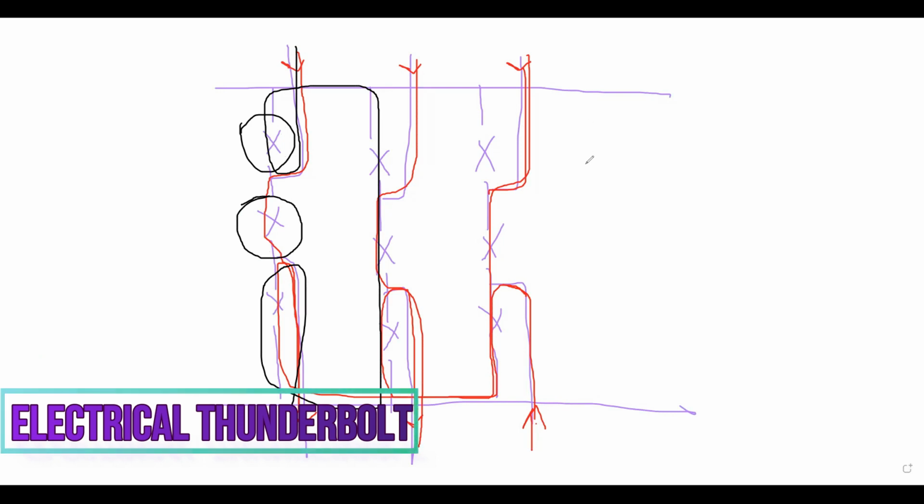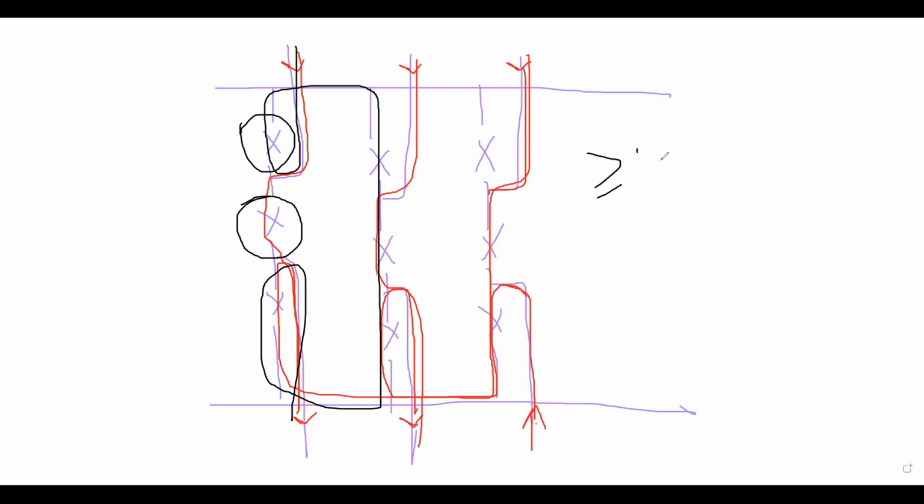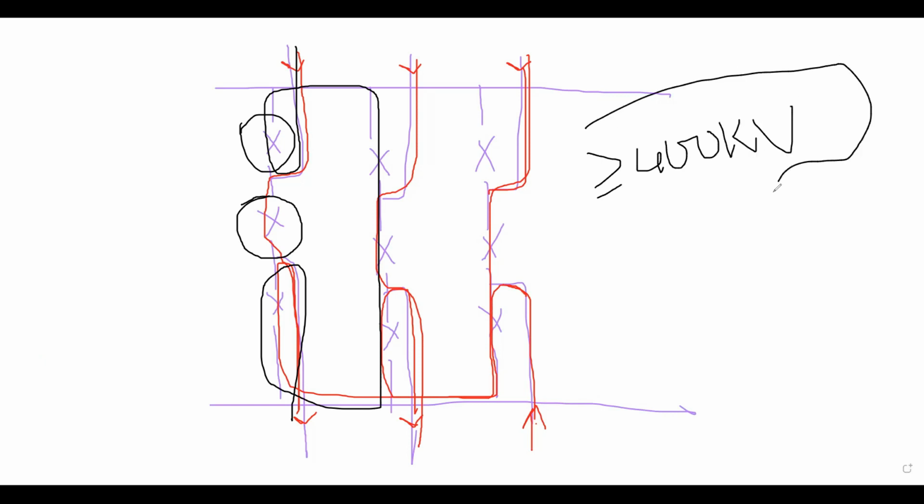This scheme is generally used in systems of 400 kV and above. From 400 kV and above, this scheme is used widely. For 33 kV systems, we will use single bus bar or otherwise single bus bar with sectionalizer scheme.